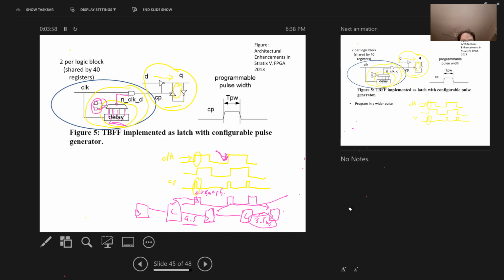There is a cost to this, by delaying this signal. Well, there's two costs. By widening the pulse on this register, when I timing analyze it, I have to assume the data comes late, okay? Which means this downstream logic better have some timing slack. The other cost is that my hold time gets harder, right? I have to make sure that there are no paths that could get through this register in that 500 picosecond period. Like there's no other logic that's really fast up here.